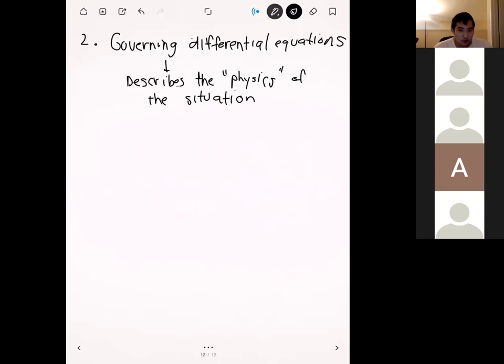And so this step, if you relate this to what we did in ANSYS, is one of the very first things that we do in ANSYS. We have to select what type of analysis we want. The one that we'll focus on most in this class is the static structural, which is saying that we want to solve a structural problem. Structural problems have their own differential equation that governs their behavior. Implicitly, what you're doing in ANSYS when you're selecting the type of physics is telling ANSYS which differential equation you want it to solve.